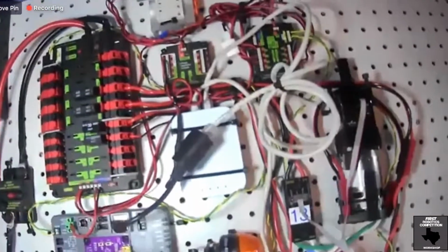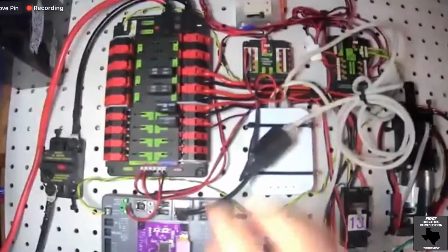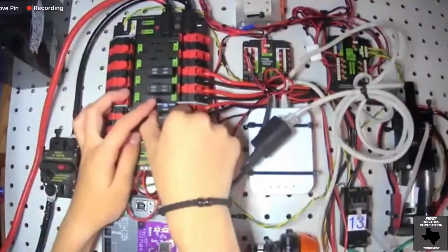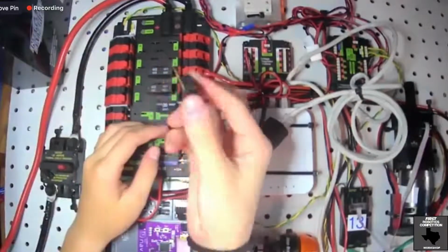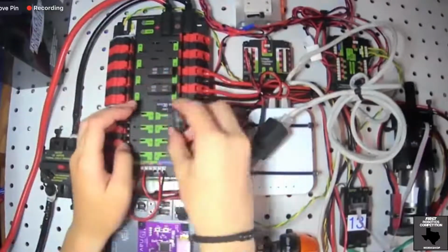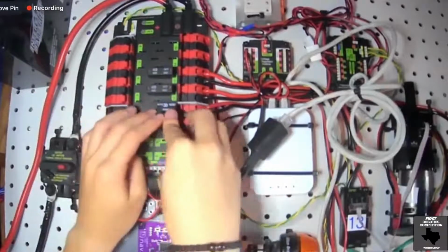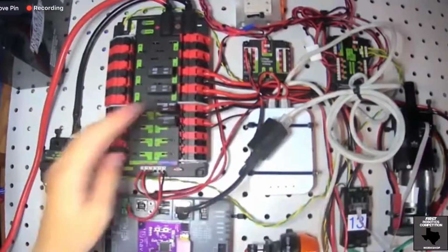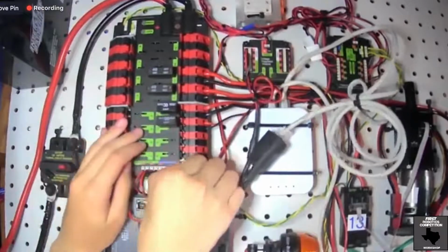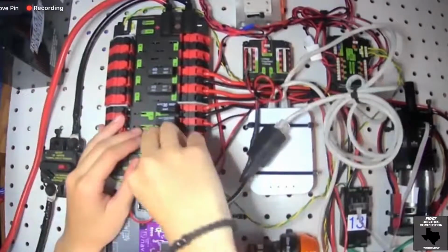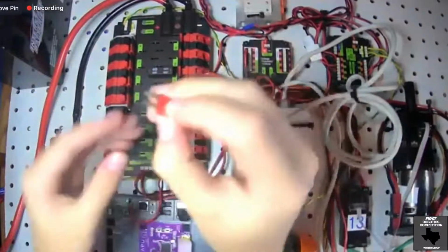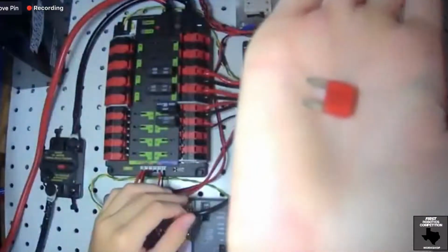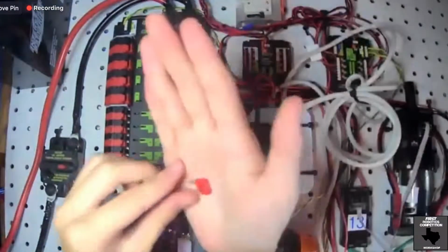Now, while Riley's pointing those out, the difference between a fuse and a breaker is that fuses, when they have too much current through them, are designed so that the little piece of metal inside either breaks or melts. Obviously, when the wire breaks or melts on the inside, current can't go through anymore. It shuts down the circuit. There's no power going through anymore.